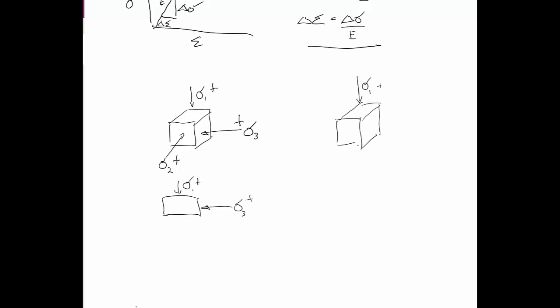Okay, now let's think about that same soil element. If I apply a delta sigma 1, so I've increased the vertical stress, what's going to happen to this soil element? So let's go back to our sponge, sitting here on the bench. If I apply a delta sigma 1 there, just logically think about it, not in terms of soil mechanics or stress analysis, what's going to happen to that sponge? It's going to bulge out at the sides, isn't it?